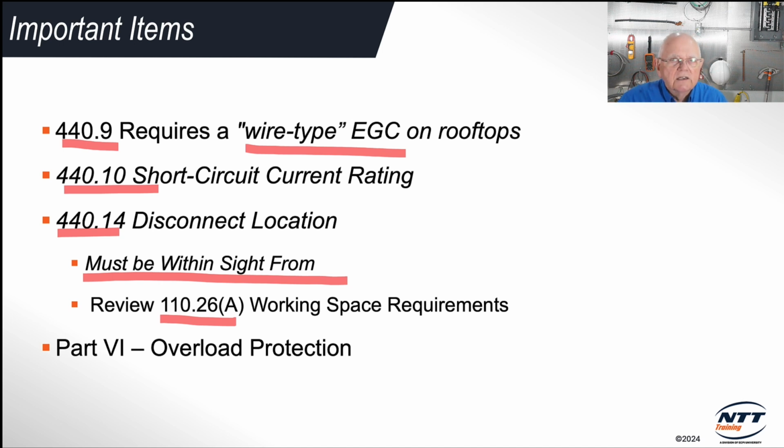And in 210.8, it's going to tell you that receptacle on the rooftop obviously has to be GFCI protected as well. Also, that receptacle or the disconnect switch, I don't want to mount it on a panel that I'm going to remove. I don't put it on the cover of a rooftop unit and I need to pull that cover off and set it over here. That wouldn't make much sense, right? So I'm going to have to mount it on something separate that's not going to be moved around.